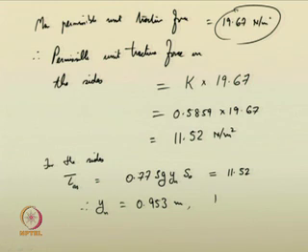Subsequently, you can calculate the bottom width of the channel. B 0 is equal to y n by 0.2, so it becomes 4.765 meter. So, when you designed, you got these two values: normal depth as 0.953 and bottom width B 0 as 4.765. Now, you check whether this can carry the requisite discharge, that is Q equal to 10, Q max. So, you have to find it.